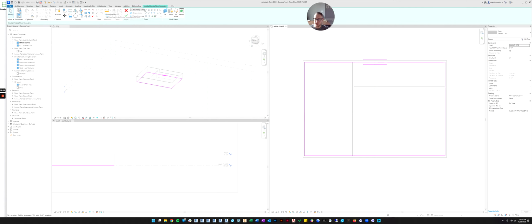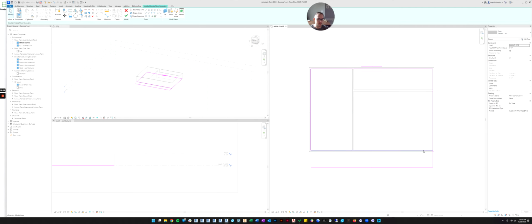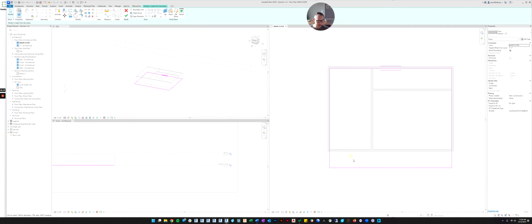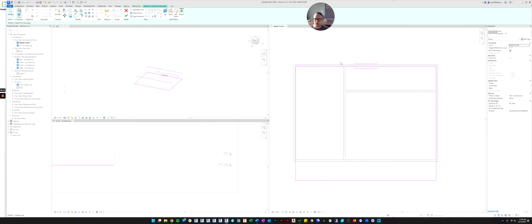So let's delete those. So maybe I also want a porch across the front. I can draw a porch. And this in sketch mode is where a lot of those commands I just taught you will come in handy. So if I select this, I'm going to hit delete to delete the line. And then we're going to use the trim command to trim that down to that. And then we're going to select this. And let's say we want the porch to be 8 feet. We're going to make it 8 feet. So now there's the floor inside the building and then an 8-foot porch.